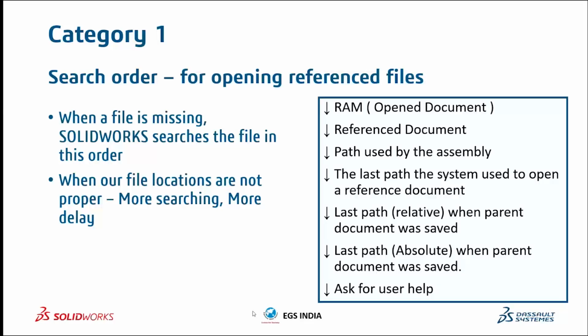So when the locations are not proper, when you don't store your assemblies within the same location, the time taken for it to search all the folders, go through the entire search order and then come up with your file is a lot. For 1 or 2 files, it may only be a very minute amount of time. But when it multiplies across 5,000 odd components, the difference in time is astonishing. So to reduce that, we prefer to have all the assemblies and files within the same location, or at least within the same folder.